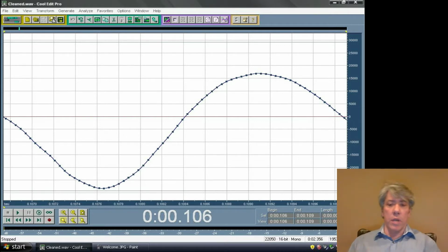If you look at the horizontal axis, the axis is in seconds, and so the first number I see is 0.107, the last number is 0.1098. So that's about 0.003 seconds, so about 3 milliseconds worth of data or so. So this whole variation happens in 3 milliseconds, and each one of those samples is a point in time where a measurement of the microphone's position was taken. So the microphone was moving down and then back up for this. It's one complete waveform.